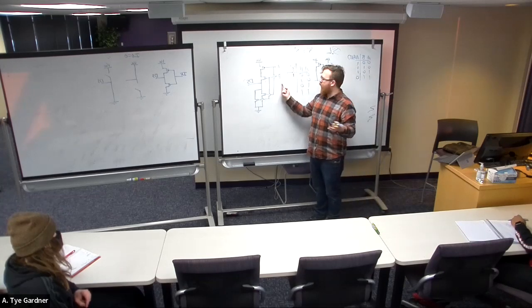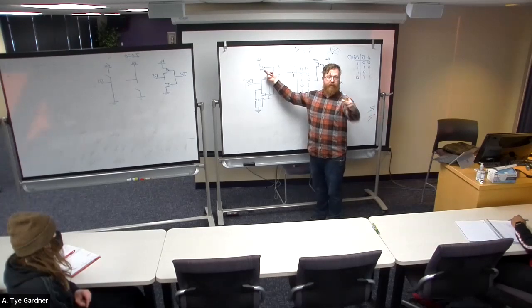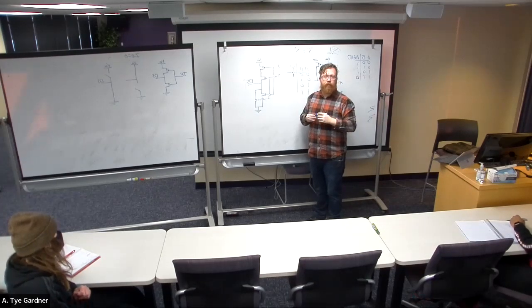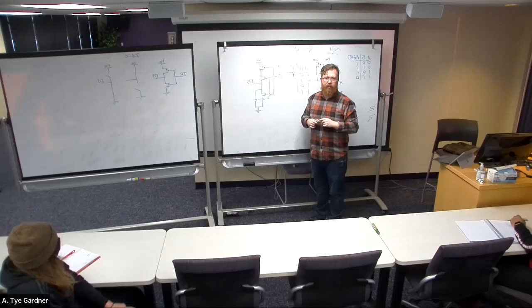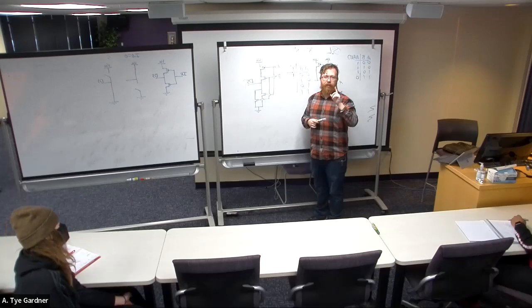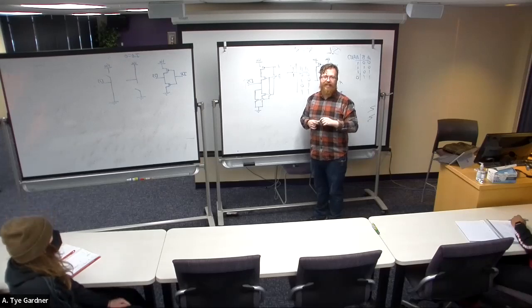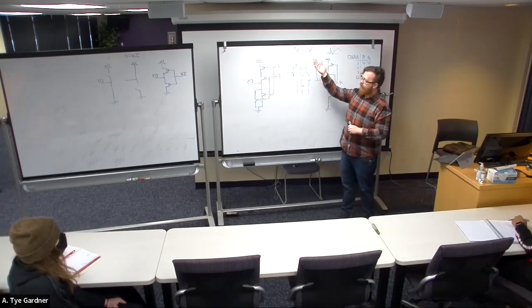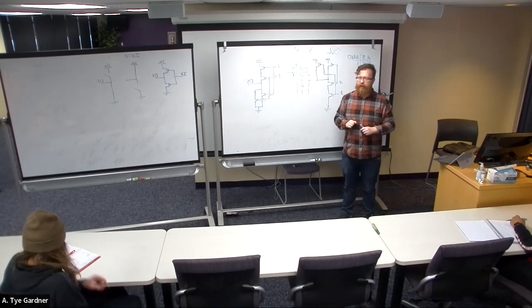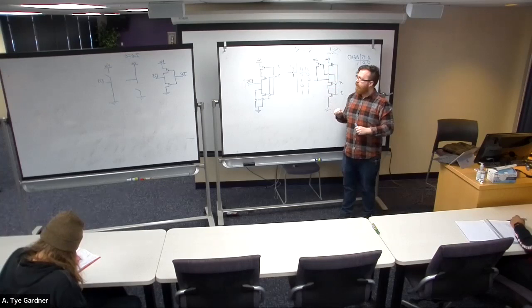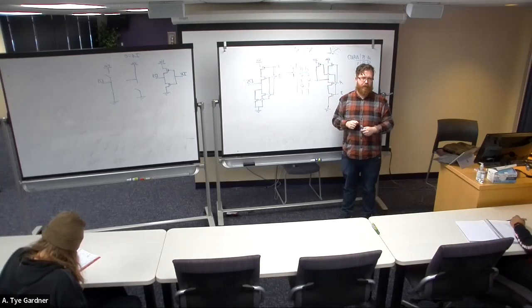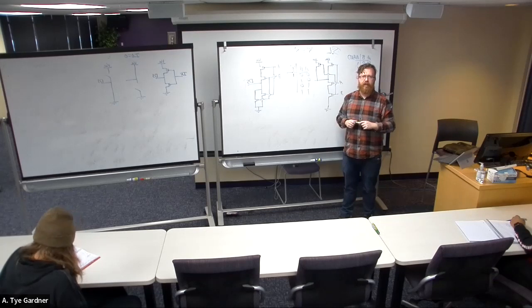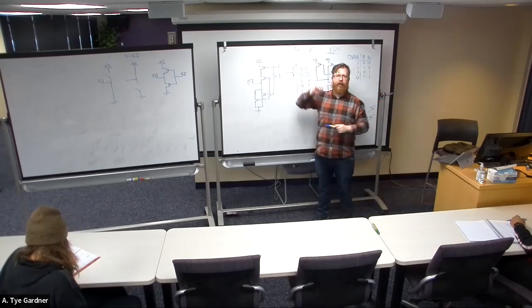They are not connected because 1 makes PMOS off. So 1 will make a PMOS off, which means it's open. Open, yes. And then a 0 will make a PMOS close, which is on. And then is it just the opposite with the NMOS? NMOS. Yes. Together they become CMOS, C for complementary. Oh, okay. PMOS up top, NMOS down bottom. PMOS acts like negative logic, NMOS acts like positive logic. Yes. PMOS pulls up, right? Yes, we will always use the PMOS as our pull up network.